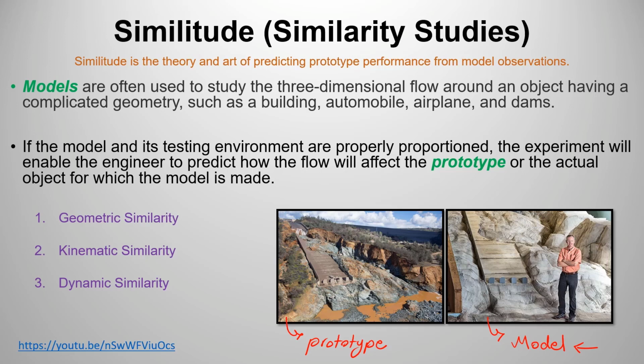So again, in the photos that I have provided, Oroville Dam had some incident in 2012 because of cavitation, and this is the spillway of Oroville Dam over here. Because of cavitation, as you can see over here, parts of this spillway were destroyed because the flow was really, really big, and the spillway was not designed for that kind of flow because the velocity was very, very high, pressure was low, those bubbles were created, and the bubbles burst, and the spillway was damaged, right?